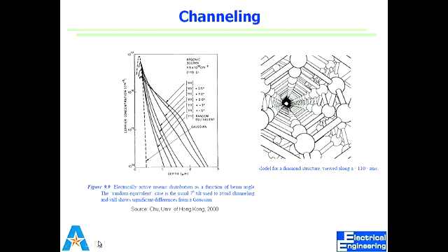We tell the vendors what angle we need for them to do ion implantation. If I use a 100 wafer or 111 wafer, the angle is very clear, right? The data is known. If I have a 111 wafer, I will be careful to define my angle, because that will define how well confined my implantation is, right?